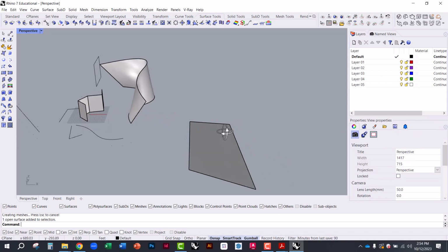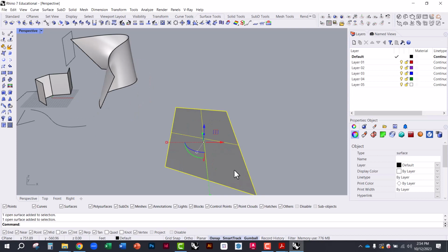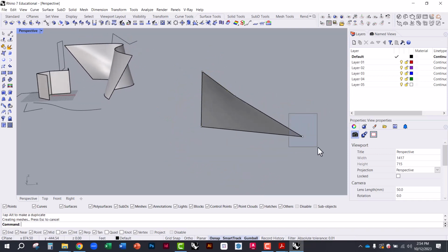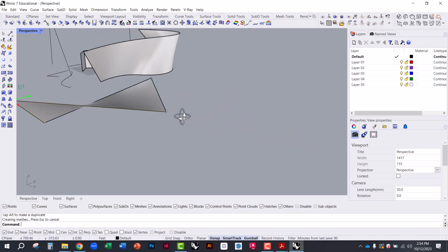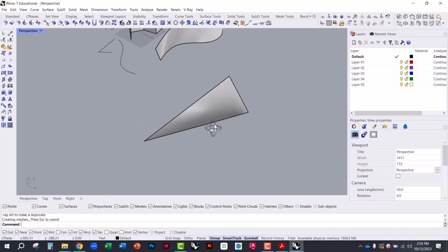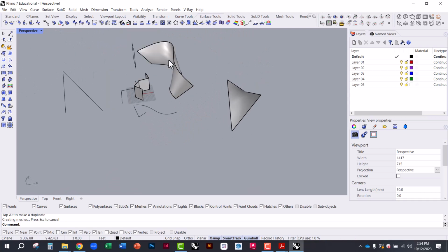And then if you select an object, you can also type points on, enter, and you can select multiple points, manipulate them, and adjust these to create the curvature or manipulate the geometry the way you want. Okay, so that's points on. That's another useful command in Rhino.